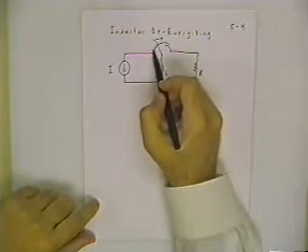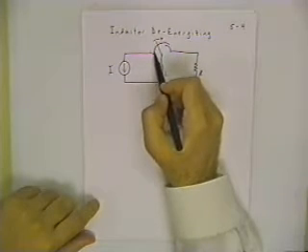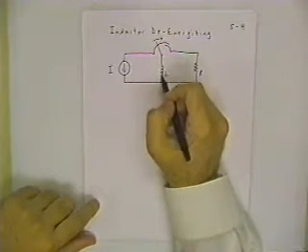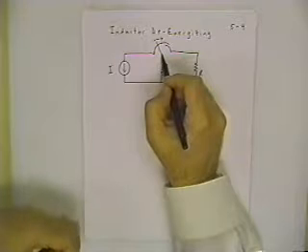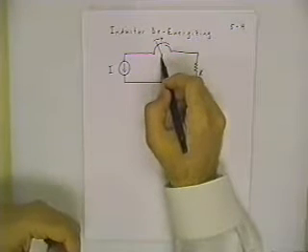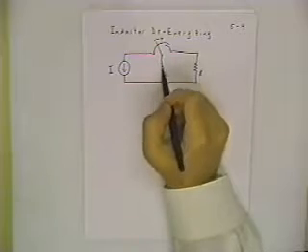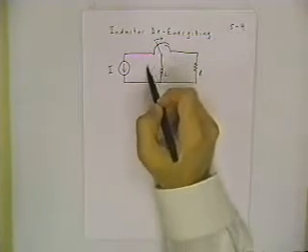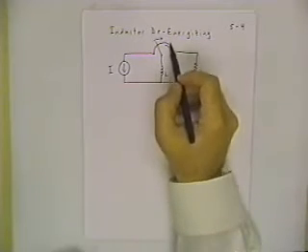If we just used a regular two-pole switch, then there would be an instant of time between switch in this position to the switch in this position where an energized inductor would have energy stored and no way for that energy to be released in a controlled way. So you'd have tremendous arcing problems, and that's just a safety hazard. So whenever I show this circuit, I always include this sliding contact switch to illustrate.